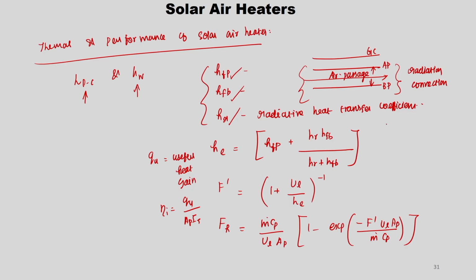But if you have, as I said earlier, a glass cover, an absorber plate, and fins attached to it through which your air flows, then the bottom plate, all of this has to be changed, because the effective area for the fluid flow will change. So, these may not be applicable. This is done only for the basic design. In that way you can do analysis for solar air heaters as well.